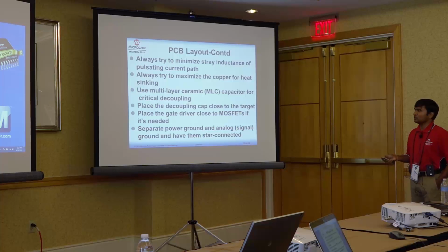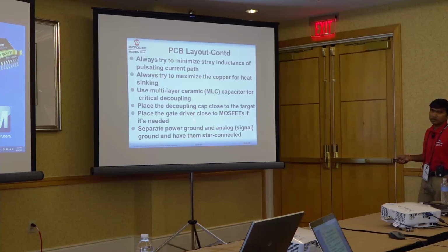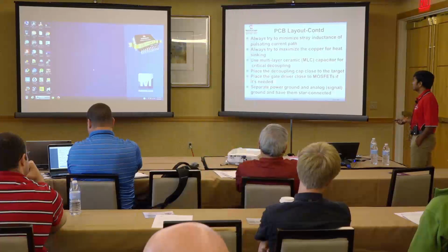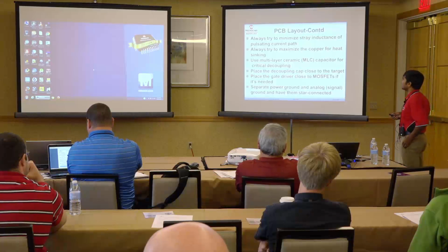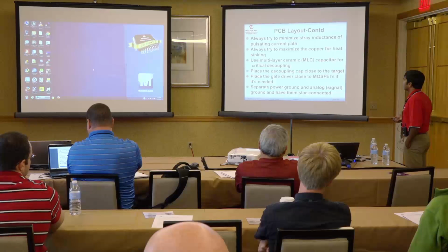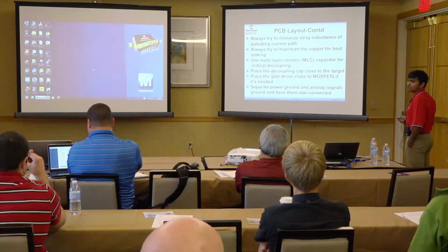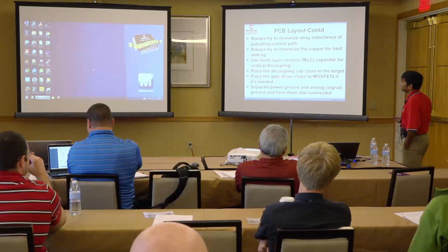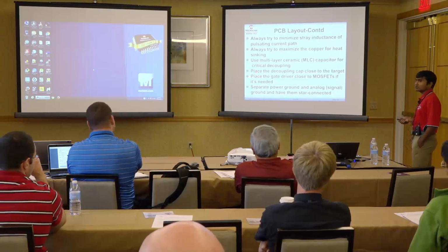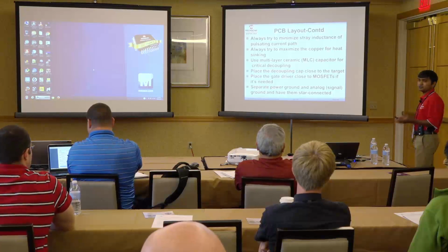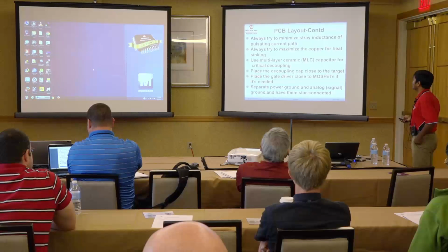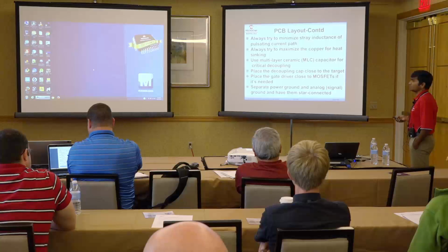And wherever possible, separate the power ground and analog ground and have them star connected, and place the gate driver close to the MOSFETs if you are using separate MOSFETs. We also have some integrated FET products where the routing becomes a little easier, but if you are using a controller, it is better to follow these guidelines.